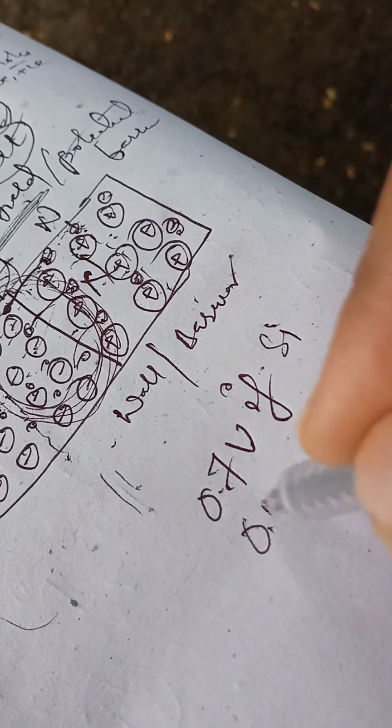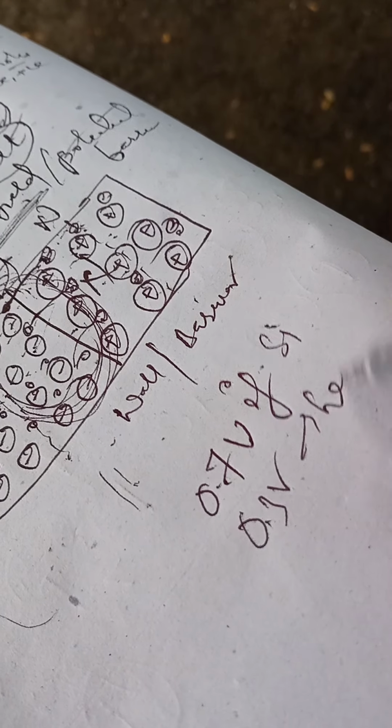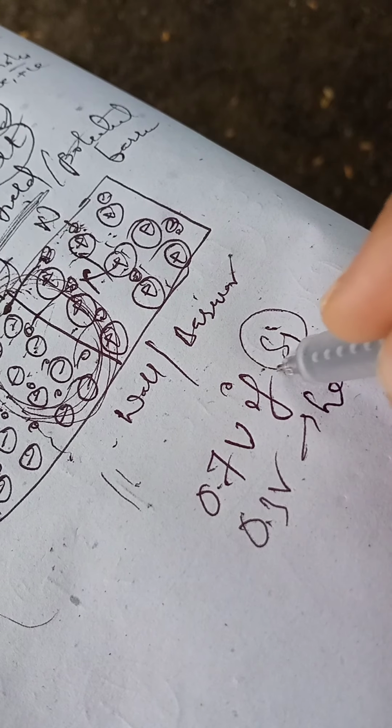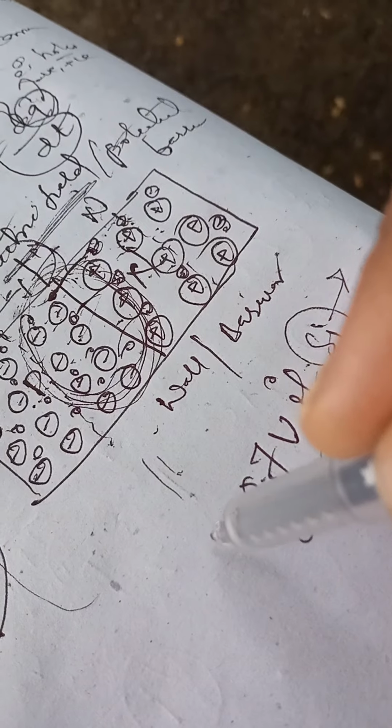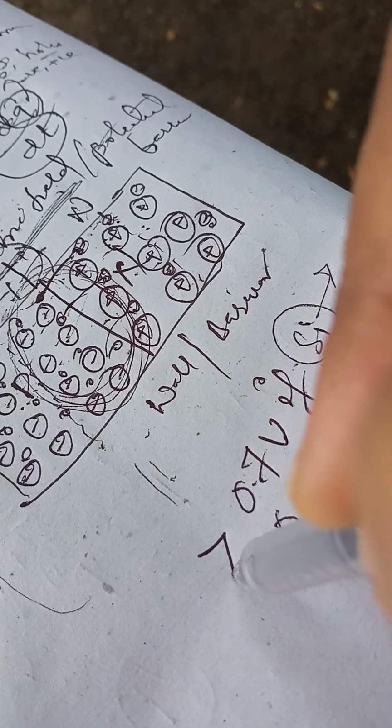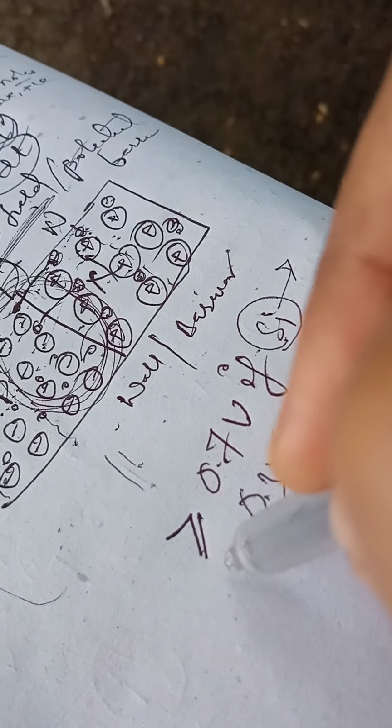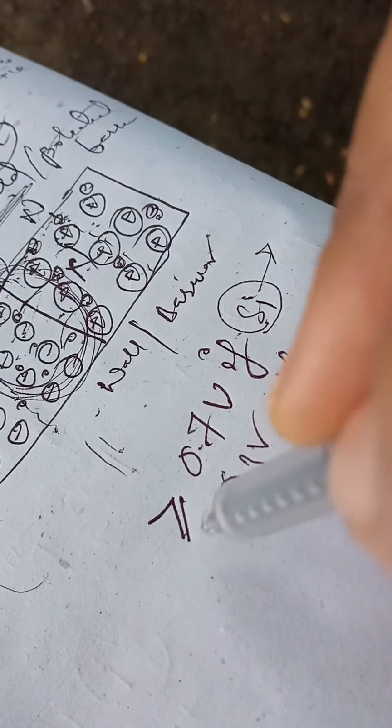and it is 0.3 volts if it is made up of germanium. So we have to check what material it is made up of. If it is made up of silicon, then we must apply an external biasing greater than or equal to 0.7 volts, and if it is made up of germanium, then it must be greater than or equal to 0.3 volts. So that's how we connect either a forward bias or a reverse bias. Then the concept of forward biasing and reverse biasing comes into the picture.